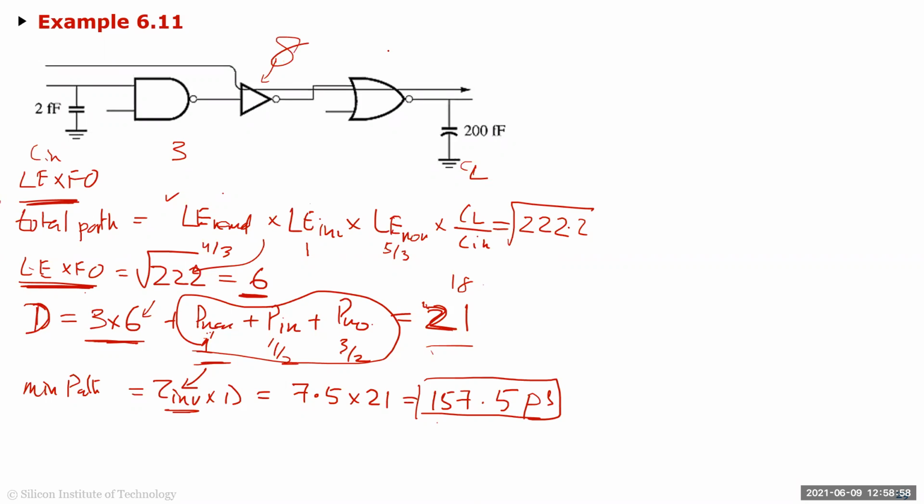Because for example, if this logical effort turns out to be more than 6, so let's say this was 8 or this was 10, you know you can optimize this because your total effort per stage should be 6. Okay, 6 times tau picosecond, tau inverter. So that's the beauty of doing this in the logical effort path.